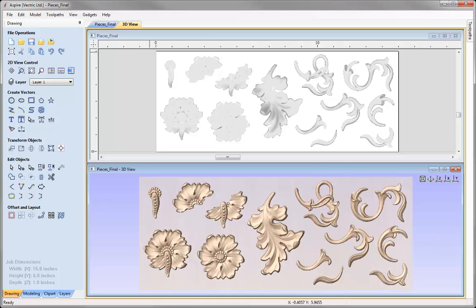So that concludes this particular example. In here we've looked at some of the typical techniques that I would use when taking an existing piece of clip art and starting to chop it up into smaller pieces that I can use to create different layouts based on that same look and feel. We looked at how important the vectors were in drawing nice accurate vectors. We looked at the trimming, cropping and splitting commands that we can use to isolate different areas of the model, and then how we might use the sculpting tools in order to tidy up any hard vertical edges we create, how we might create additional pieces or additional shapes using the Create Shape or the 2-rail sweep tool in order to join or finish off the ends or edges of my parts as well.